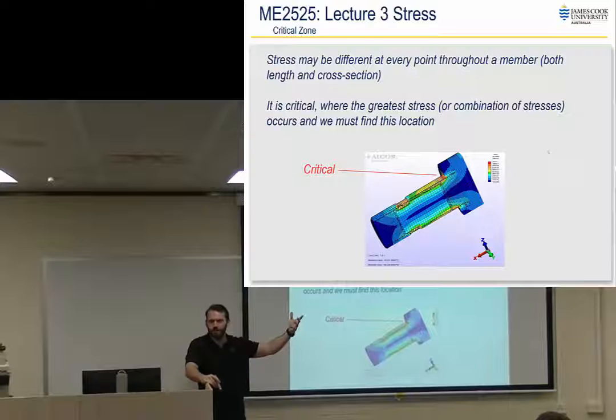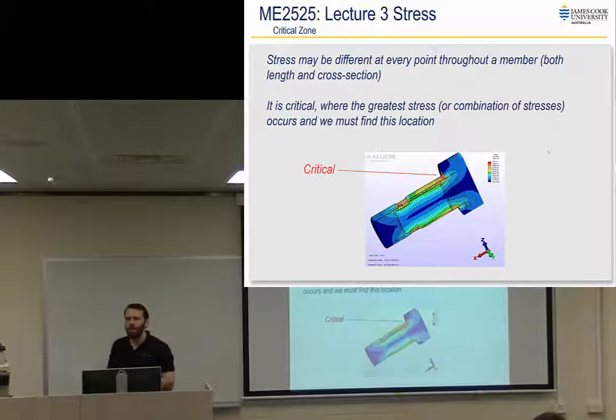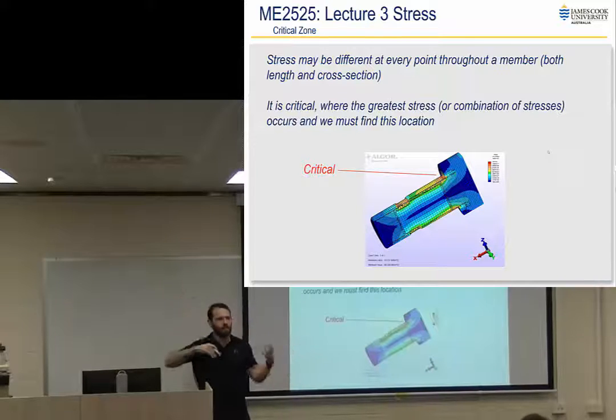At a larger level, that becomes a crack, and as soon as you have a crack, that becomes a proper failure and things start breaking and spitting pistons out of engines and so forth. So what we're interested in is avoiding that. The way that we determine that is stress, because if you know the stress and you know what stress something will fail at, then you can compare to that and make sure that you're under it.